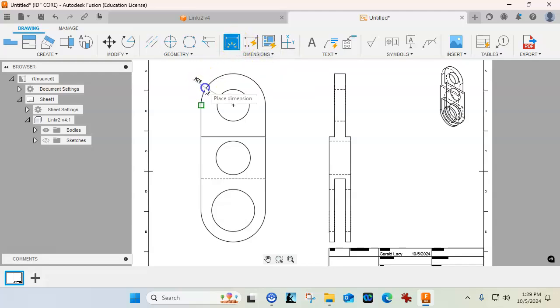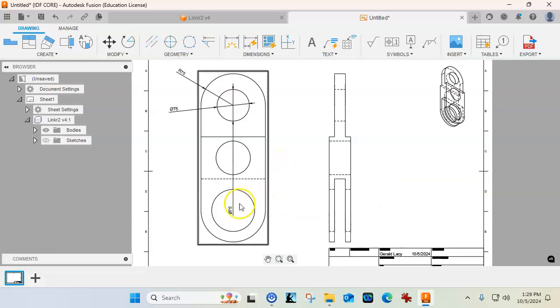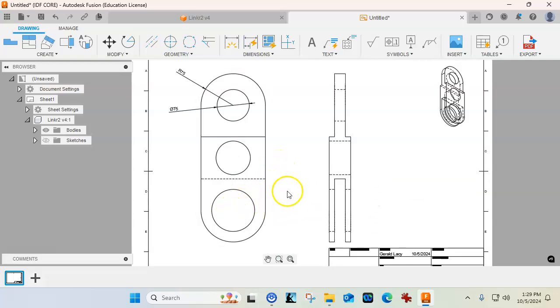For the dimensions, kind of like in the sketch, we're just going to start applying our geometry. Radius 0.75, we can go between the center points. And it's saying it is not an object, so it pulled the 75. I also could have hit undo. So let's go with the center mark then, and we'll go ahead and apply those. They're a little bit easier to dimension to for the centers.